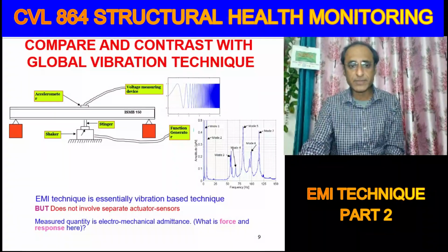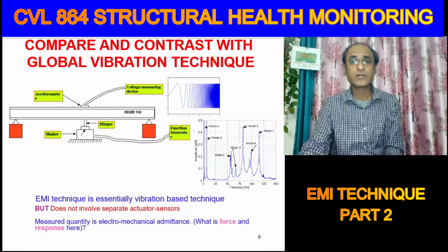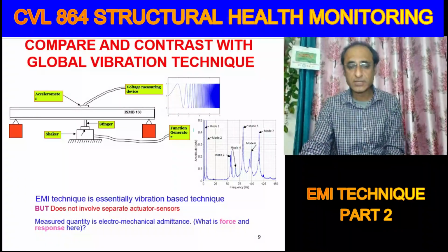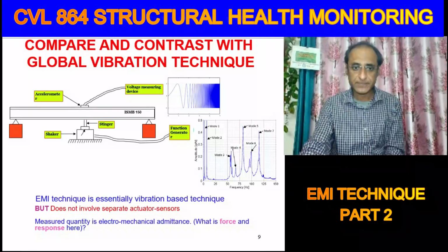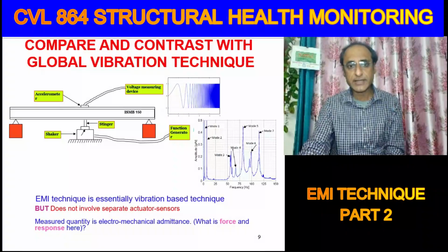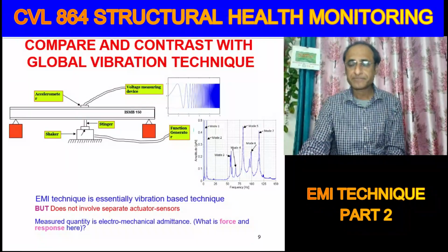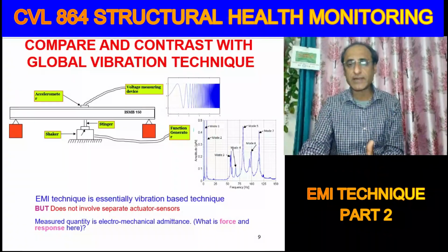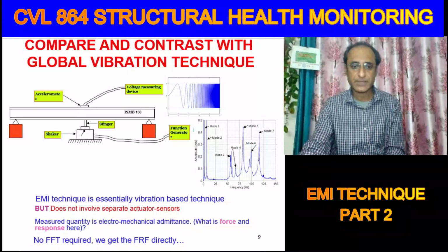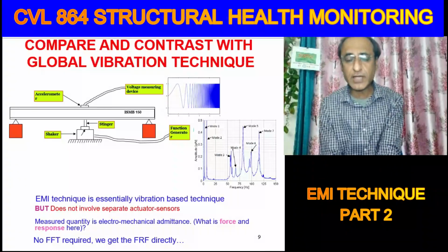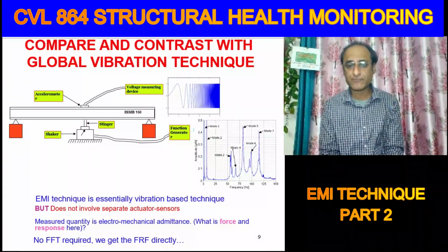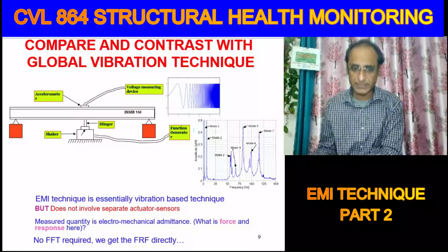Here we are measuring not acceleration or displacement or strain, but an electrical parameter, the admittance. That is also like an FRF because we are applying some kind of excitation and then obtaining response. So here we are obtaining the data directly in the frequency domain.